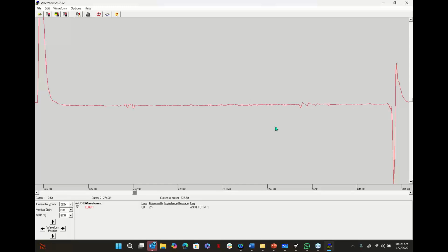But here's the deal. If I told you that there's another way to minimize ghost reflections inside your cable under test, would you take my advice? I would if I were you, because I've been doing this a while. If you use a longer jumper, that is another way that would make these ghost reflections go away. How long are we talking?